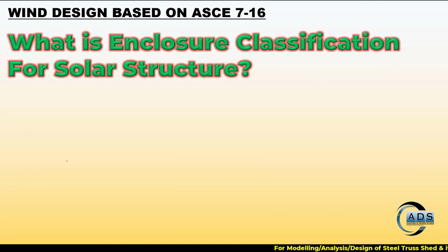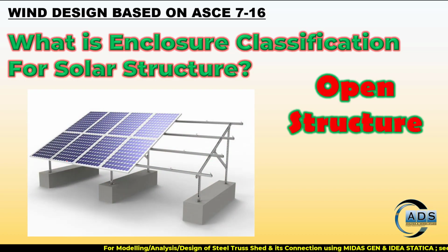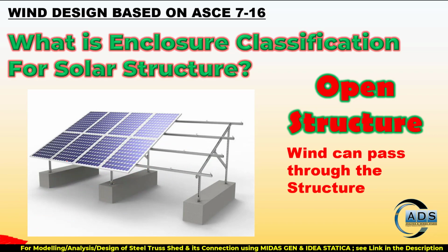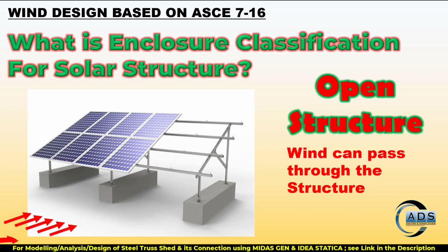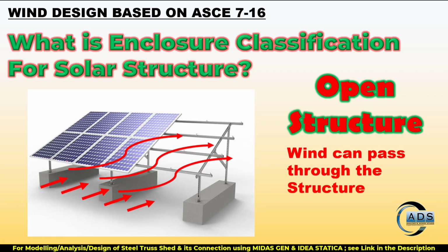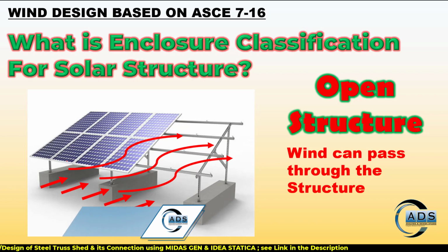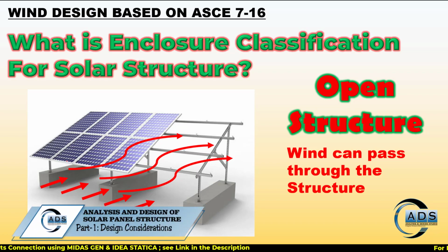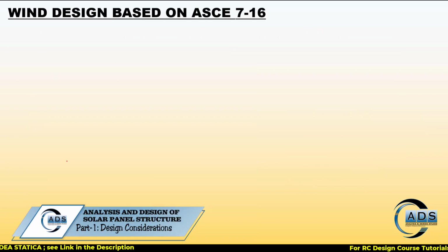So what is the enclosure classification for the solar structure? An open structure, because wind can pass through the structure. When wind is first hit the structure and then can easily pass through the structure, alright? So that is why it is considered as the open structure.